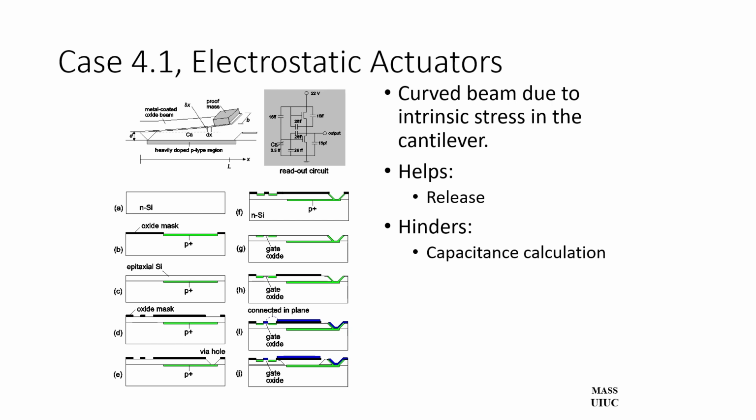You have an intrinsic silicon substrate and an oxide mask is placed on top. It is patterned and the oxide is etched to expose the silicon.